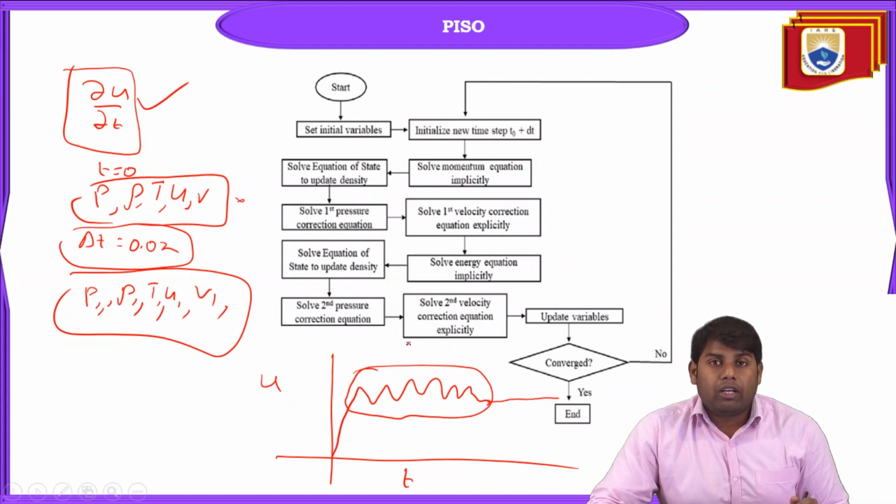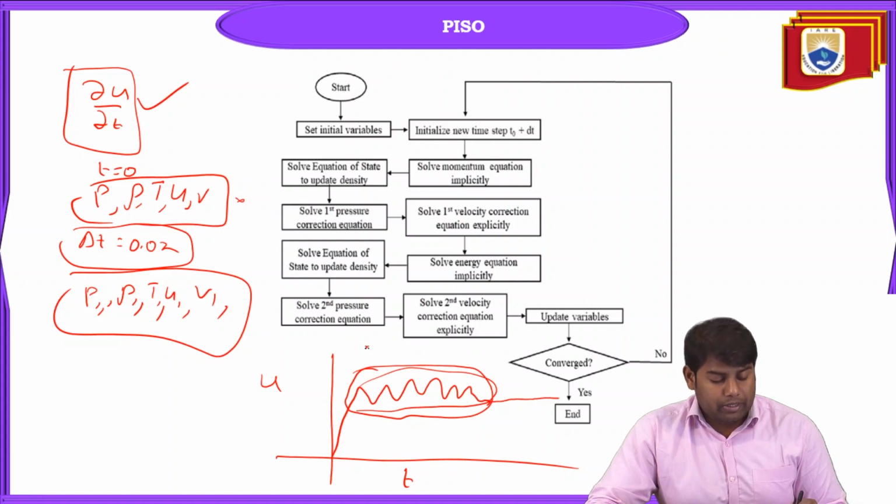Why? Because of the value we are calculating from the boundary points to the internal points. During the calculation procedure and while the algorithm is solving, we have to see the residue contours also. These oscillations are because of the unconverged portion of the simulation, where the error still represents this oscillation. Once the error is decreased and the simulation is approaching convergence, then you have these steady state solutions.